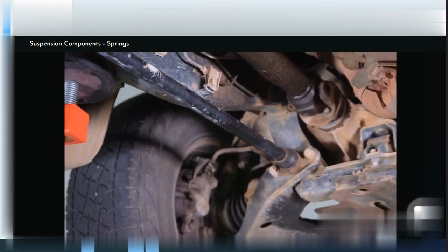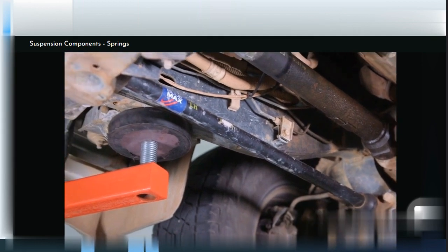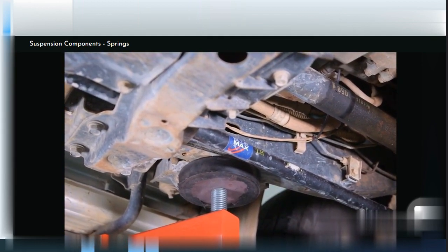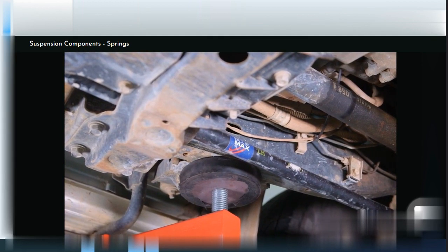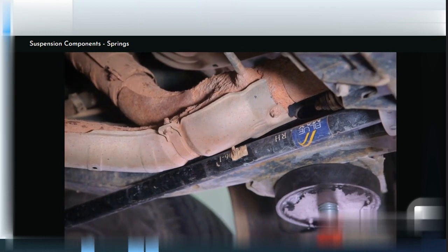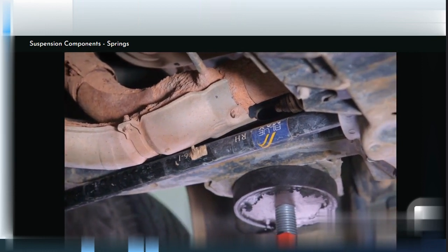Torsion bars are used in four-wheel drives and commercial vehicles. They offer easy preload and ride height adjustments, but take up less vertical space than a coil spring. Torsion bars are pre-stressed, and as such, are designated left or right only.